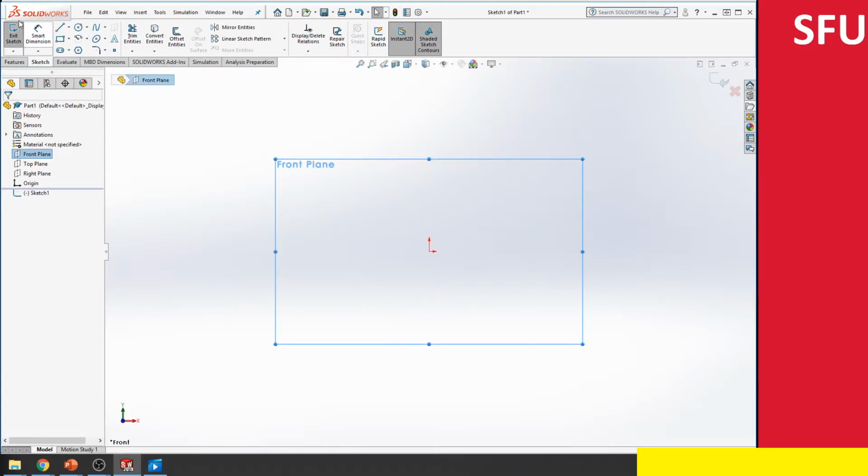You also notice that things have changed on the top menu over here. This is the context menu that shows up. If there's an issue for some reason, you click on the sketch over here, which will bring up the corresponding menu. If I move the mouse, it gives me a hint, and it also tells me it's a line. If I move it further, it tells me there's a circle and so on. And then it gives me a shortcut that I would use quickly. And the thing you would notice is beside all of these, there is a smaller drop-down menu over here.